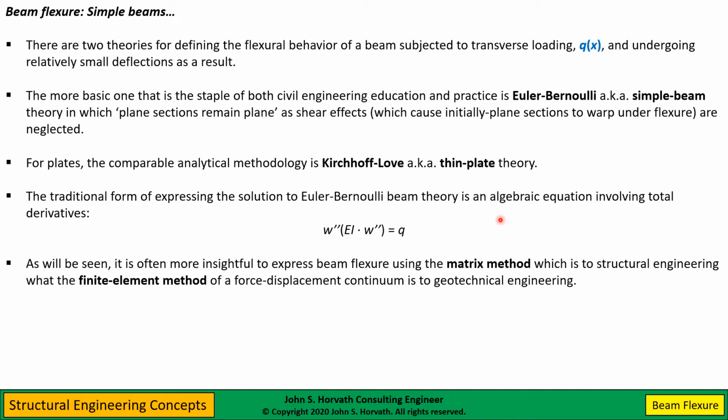Certainly throughout my career, I've become a bigger and bigger fan of the matrix method in structural engineering, which, as you know, is to structural engineering what the finite element method of a force displacement continuum is to geotechnical engineers. Geotechnical engineers like to break a continuum into 3-dimensional bricks, if you will. A structural engineer, she or he, likes to break a structure into sticks, if you will, and connect the sticks. Not to trivialize it, but it's really the main difference between the matrix method and finite element method.